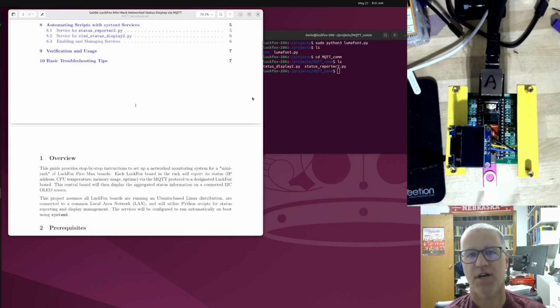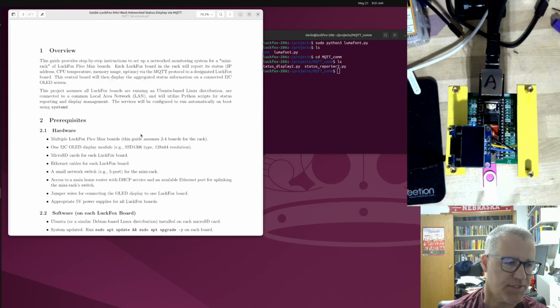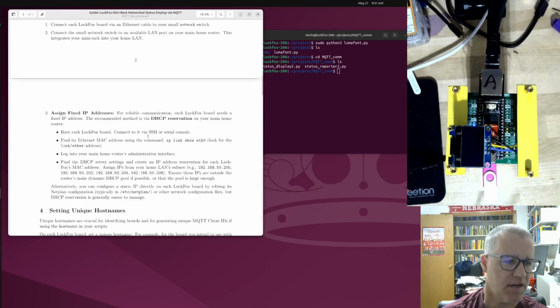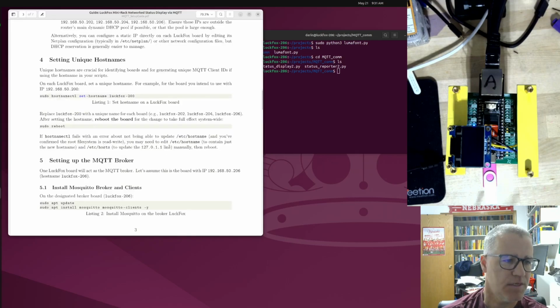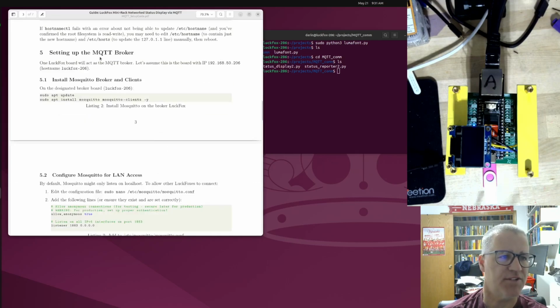And so we'll set up 206 first as the broker and what it needs to do. Then we'll set it up as the client, and on the other LuckFoxes, all you have to do is the client side. You don't need to do the broker side. And just for the sake of time, I won't do all of them in this video. So let's get started here on section 5, setting up the MQTT broker.